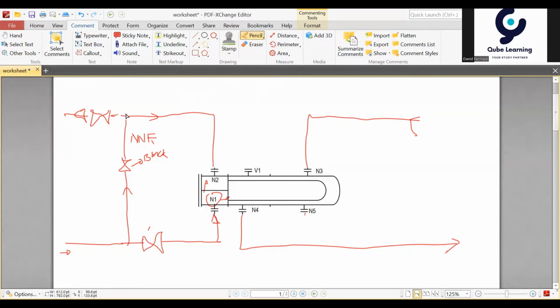During the backflush of the exchanger, we have to open the backflush line. It shall be open, and then close this block valve, so the water will circulate in reverse from usual. The normal operation is normally no flow. We also need to close this block valve.